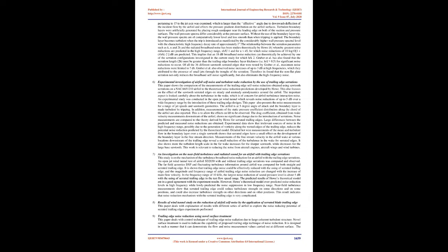Therefore, for a fixed serration geometry, high frequencies are preferable in terms of noise reduction. This also means that the root to tip length determines the effective frequency range where sound reduction can be achieved.